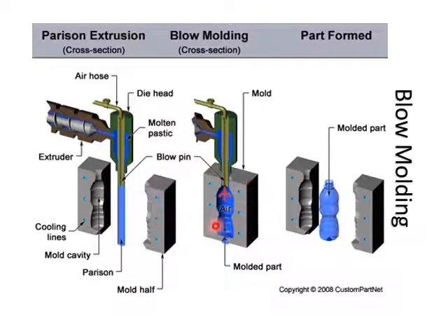Over here for the mold, and then over here you have an air hose, and then the air will be pressurized to blow out the original rod material into the shape of a bottle. Then the mold is released to get the final product.